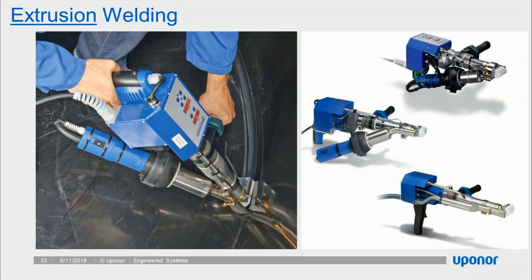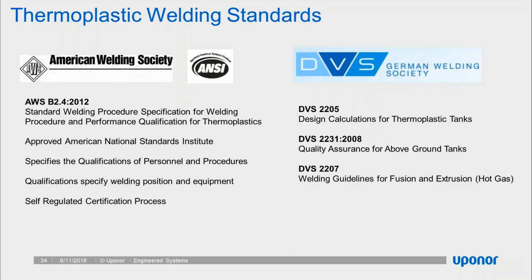Here you can see an operator working in a Wagner extrusion gun, heating a polyethylene vertical riser and a HDPE base. You can see the dull appearing haze that follows that weld is a quality weld, and the thick molten mass of material that's bonding those two materials together.